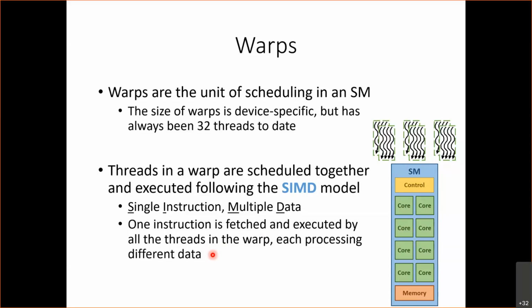So will the warp finish once, and all the threads in the warp will finish at the same time? I mean, that's the result of the warp having SIMD. But the benefit of it is that, as somebody wrote in the chat, you're absolutely right, we decode it once. When we fetch an instruction, it's not just about the memory footprint of fetching, we also have to decode it. And decoding that instruction requires some kind of controller that is looking at the fields of the instruction, figuring out what this instruction is, and telling the different units what to do with it.